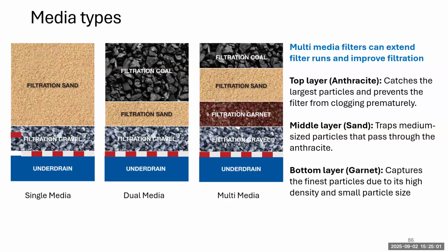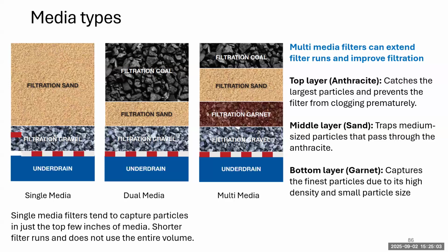And if you had a single media filter, it would tend to capture all the particles in just the top few inches, and it would become clogged. So you'd have a shorter filter run. It's not using that entire volume very effectively.